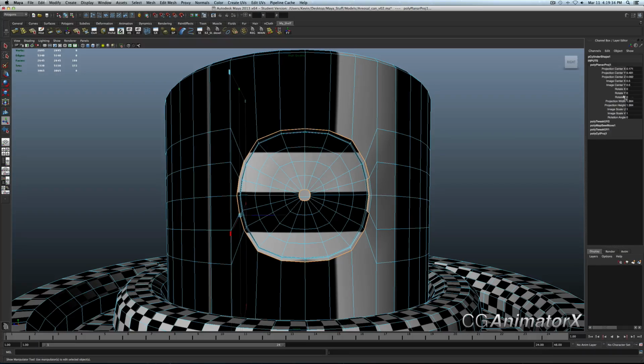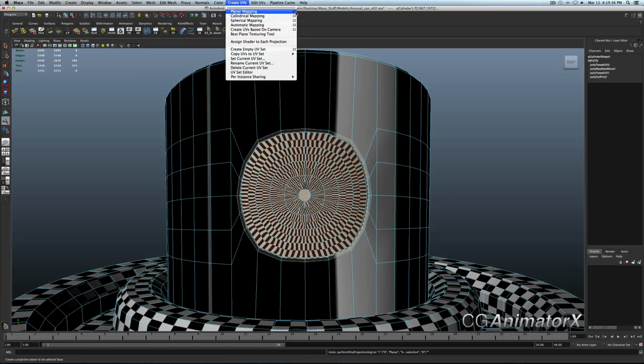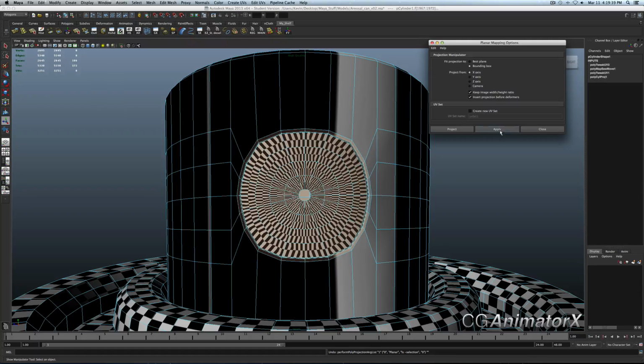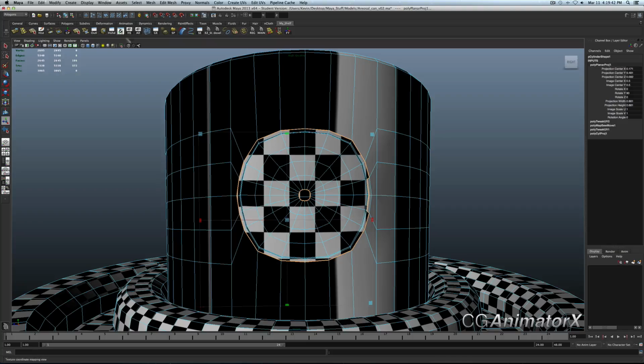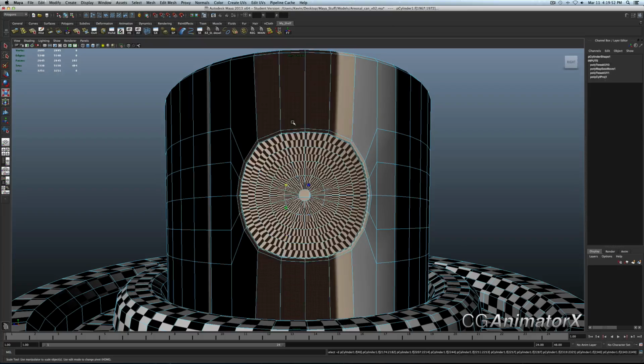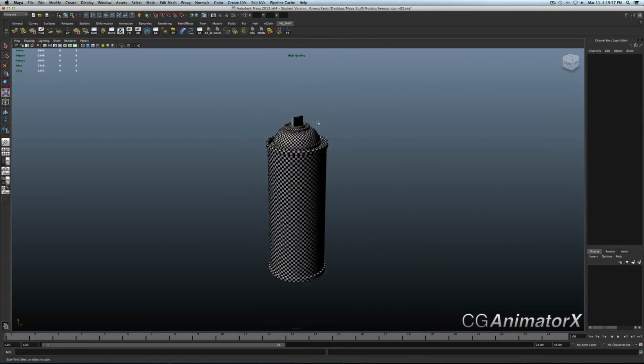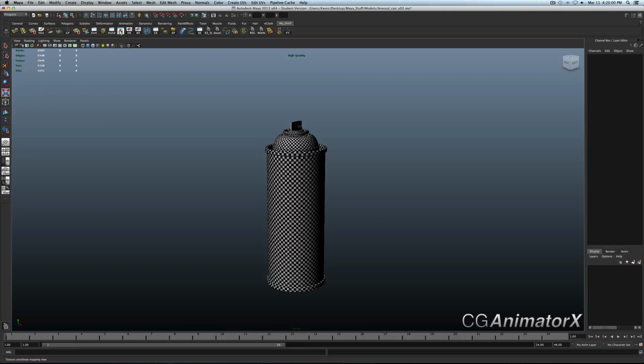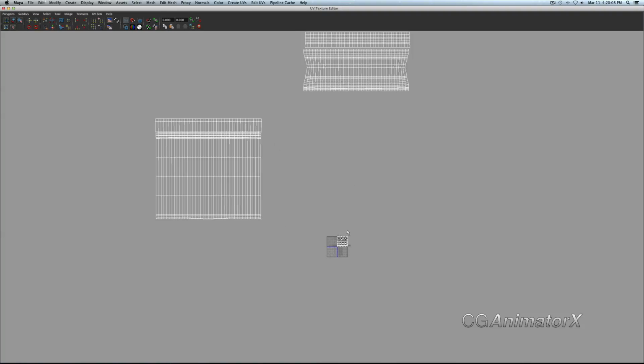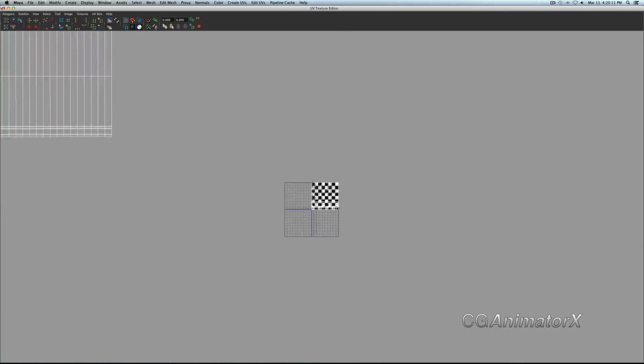on that from the x-axis or wherever your camera's pointing, and then use that as a separate piece because we're not going to attach it through there. So you would end up basically having something like this, but it wouldn't have all those other pieces on it. But that's pretty much it for the unwrap. And then for the next video, we are going to go ahead and scale all of the UVs down into our 0 to 1 space in our UV texture editor. So we're going to scale these down, and then we're going to export them into Photoshop.